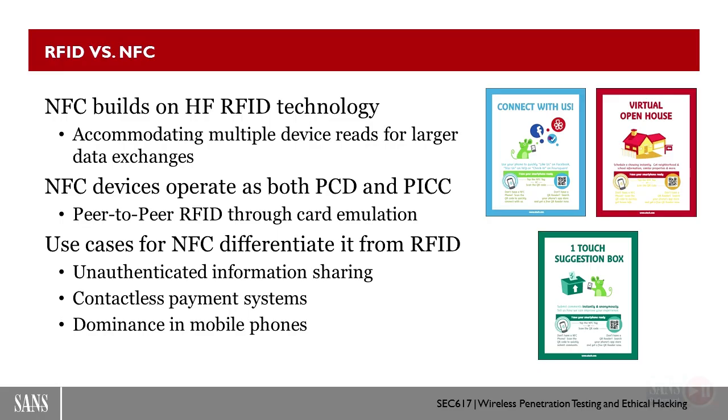And this becomes interesting in that we can now expand the use of this technology because we can do the bidirectional transfer. We can potentially implement some application layer security. And we can do larger data transfers with those multiple reads. We're typically seeing NFC's adoption in the mobile phone market, given that there's a reasonable amount of power there as opposed to something like a smart card that is powered by the environment.